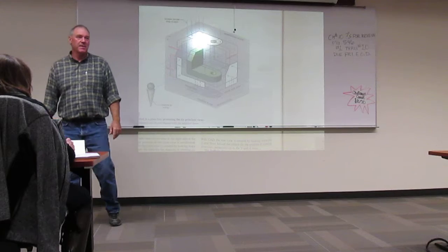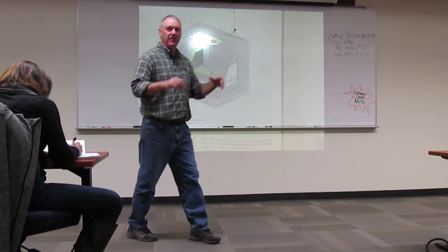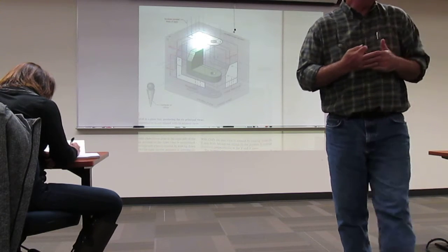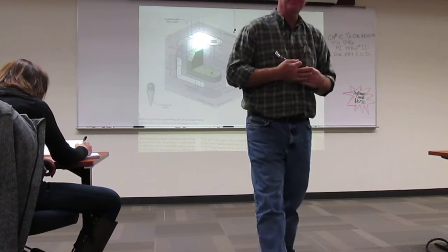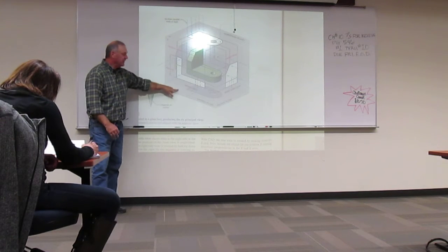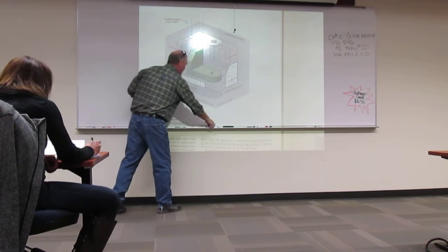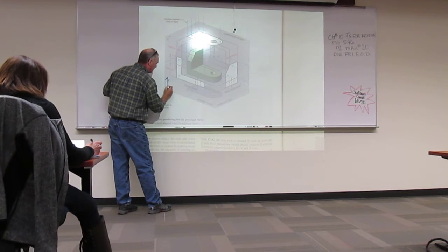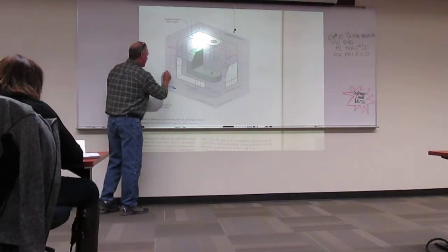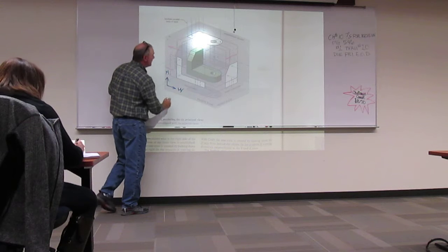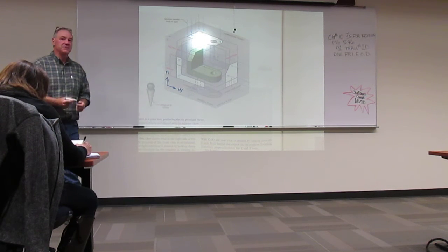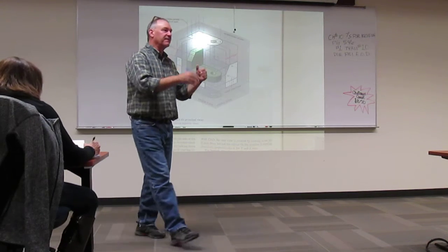Now, the important thing to remember here, the frontal plane, that's where we look at the front of the object. Since it sits in a cube, this produces 2 views. It produces the front view and the rear view. Now, what dimensions go with this plane? So if I was to come in here and say, there's a couple dimensions that go with this on the frontal plane. Height and width. Yep, I've got height here and I've got width here. So all views that are created by the frontal plane will always show you height and width. This is our front and rear views.